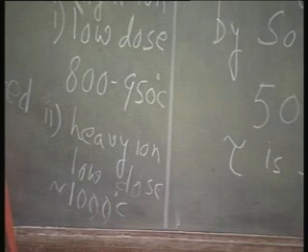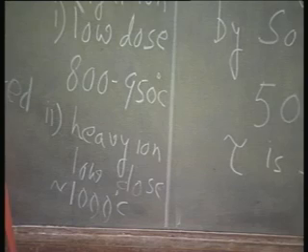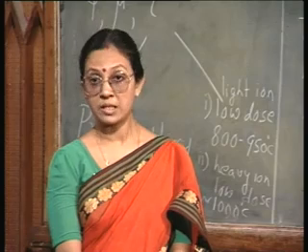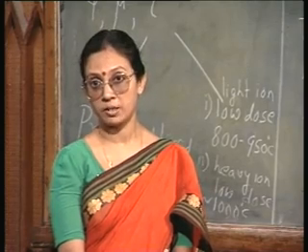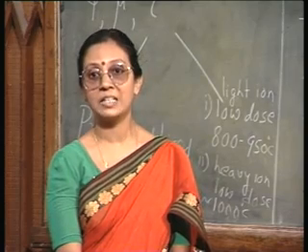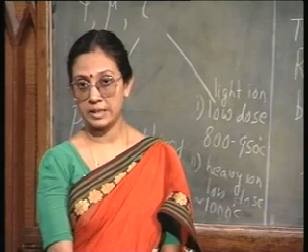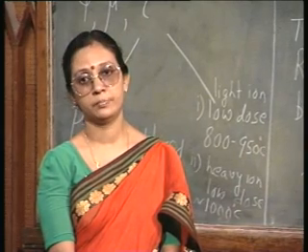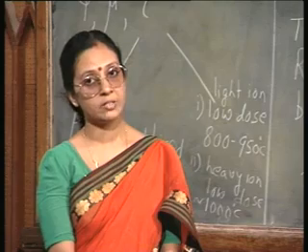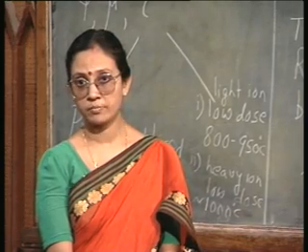But if you have heavy ion in high dose and still it is not pre-amorphized, that is the dose is not high enough to make it pre-amorphized, then you have a problem. It will be very difficult to get full activation.